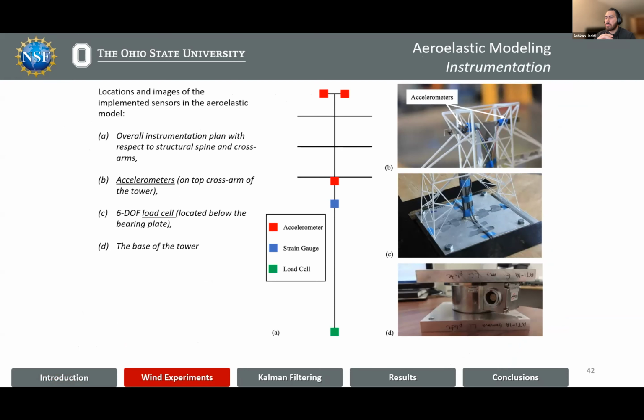One of the most important steps in this type of analysis is the modeling of wind-induced loads. ASCE manuals provide suggestions in terms of static equivalent methods for wind force modeling. The magnitude of these forces is dependent on several factors, and specifically the drag coefficient is suggested to capture the effects of the shape of the structure on wind forces.